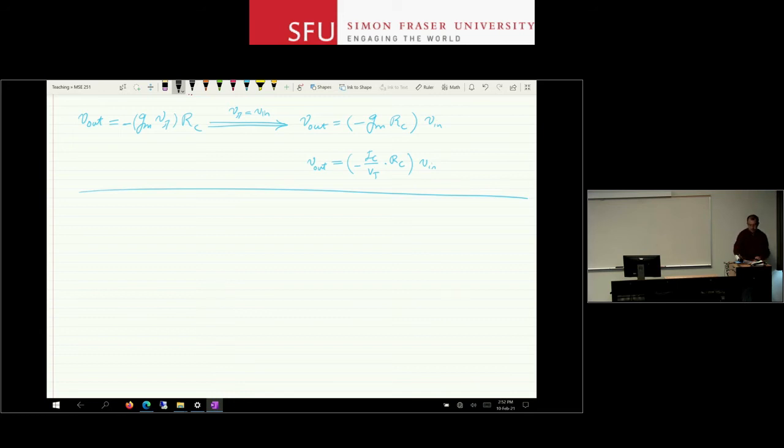We talked about this briefly in the beginning, that a linear amplifier, because it is not producing a signal for small signal analysis, when you look at it from the input port, you can consider it to be a resistor. And when you look at it from the output port, there is a dependent voltage source plus an output resistance, right? So these two parameters are very important.